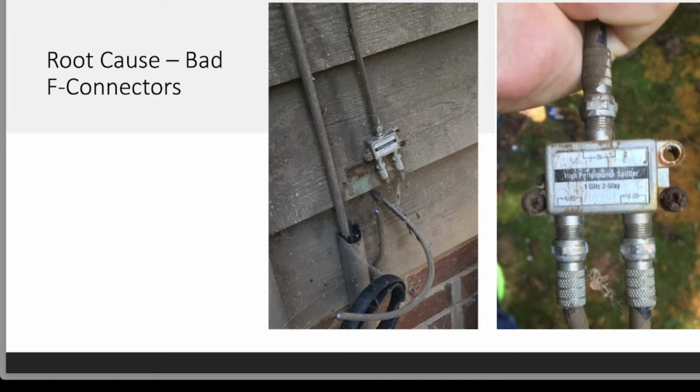No compression fitting. For anyone listening to the audio here, we're looking at a two-way splitter where on the input side is a really old weathered-looking twist-on F connector, and on the output are two weather-worn twist-on F connectors. So basically we cut these connectors off, and also replaced the splitter with new compression fit connectors.